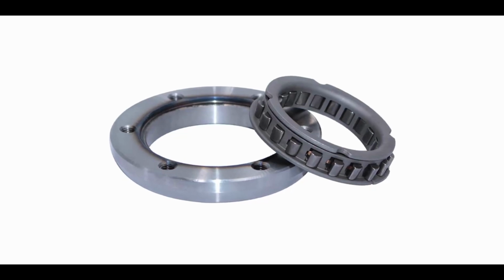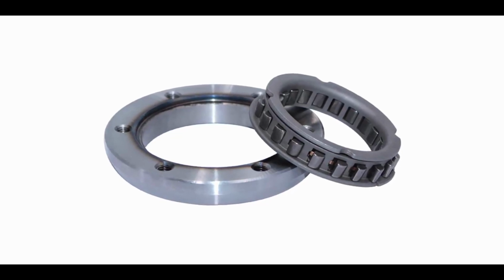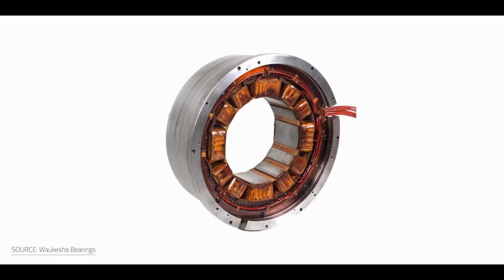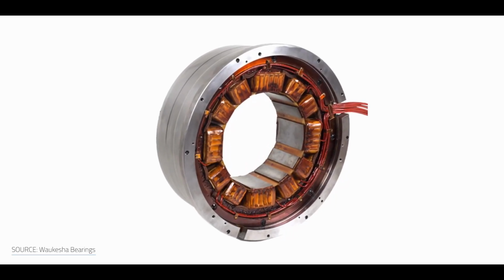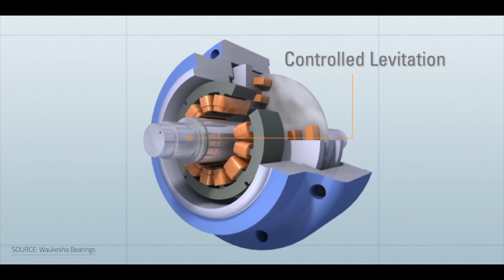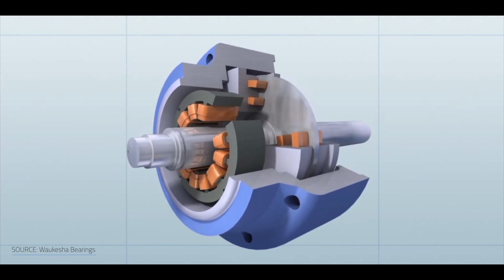Mechanical bearings require high-performance lubricants and frequent maintenance to operate properly, and they're also sensitive to the friction that they generate, and that's one of the main losses for flywheels: friction. To solve for that, expensive magnetic bearings are employed in flywheels that operate at high speeds in order to reduce maintenance basically to zero, since they don't require any lubrication at all. It also helps to increase efficiency due to their minimal losses.